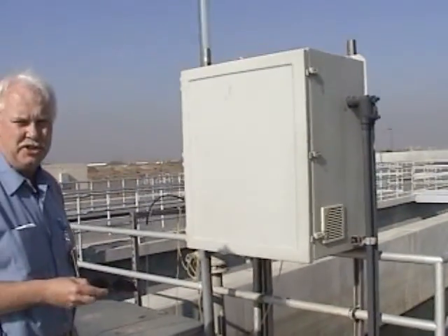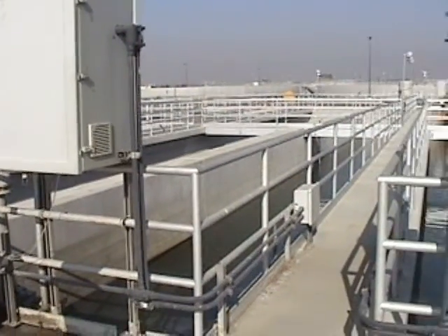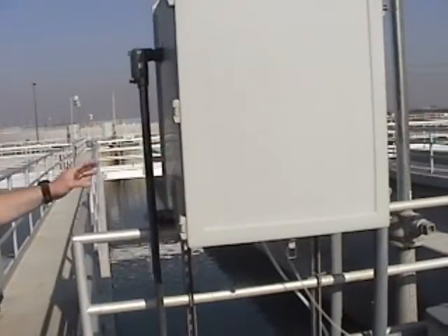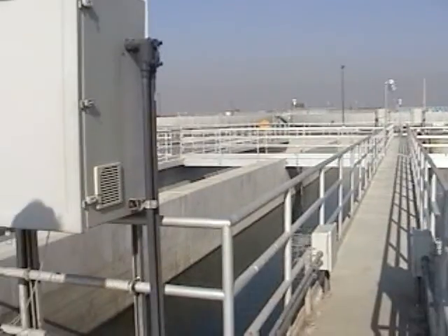We do titrations during the daytime to verify that the analyzers are running correctly. What you want to watch for though is the analyzer's control signal is fed into the plant's effluent flow times this residual, and it computes the SBS. So if you lose an analyzer and this goes to 0, it's going to tell the sodium bisulfite or dechlorination system you don't have any residual, so there's no need for sodium bisulfite, which is going to begin decreasing the sodium bisulfite.